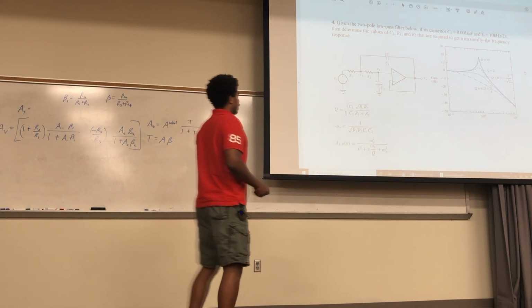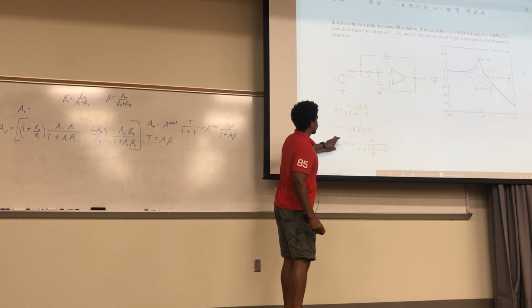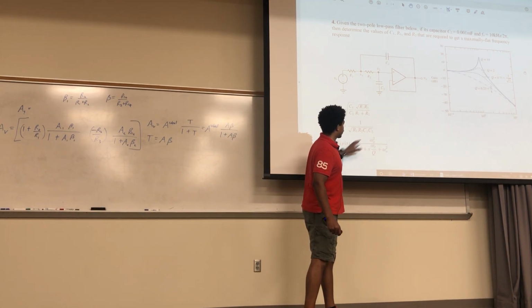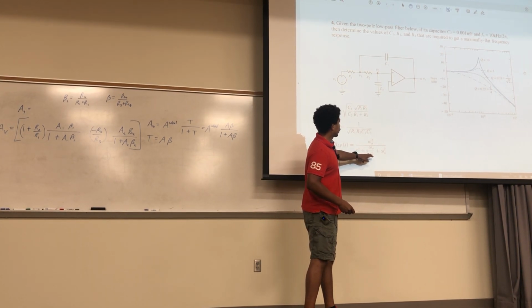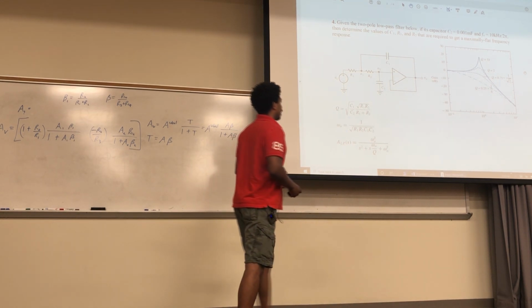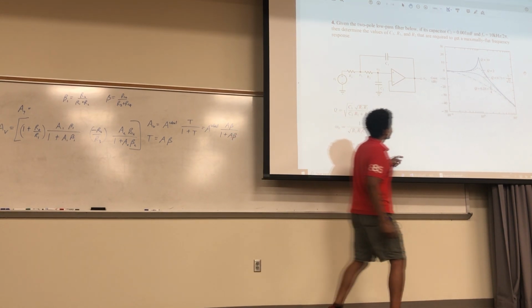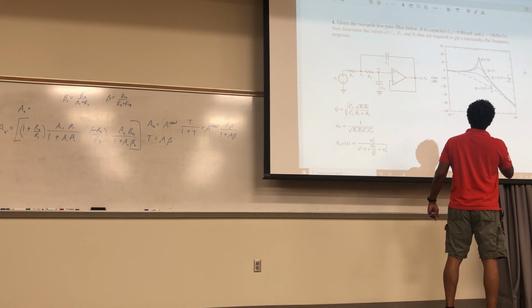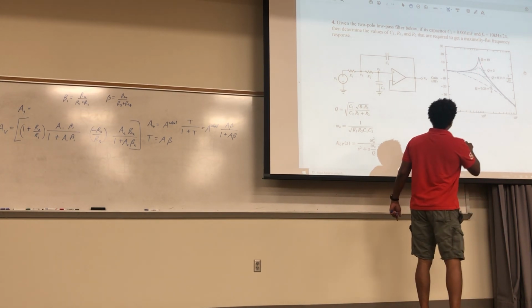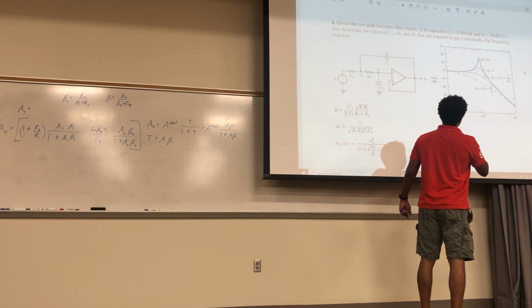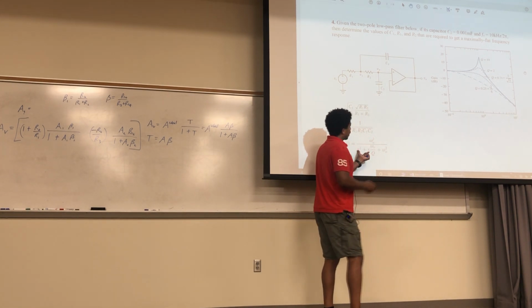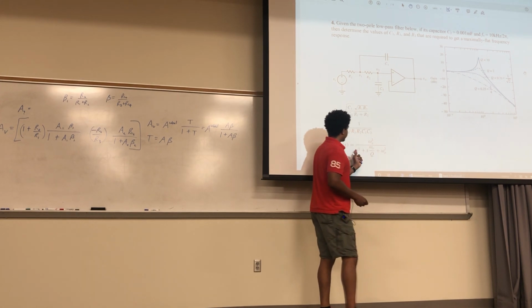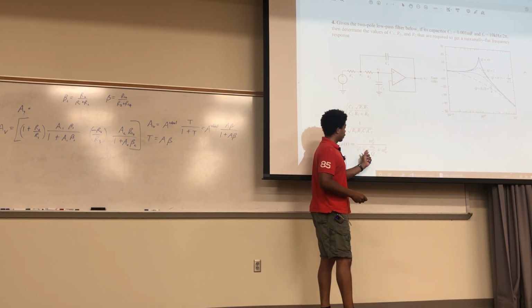Okay, and this is the second-order low-pass response curve that's being plotted over here for different values of Q. The frequencies right here are all the same. These right here are not resonating, but these right here are. That's the omega 0. The omega that's being plotted along the x-axis is in here, j omega.